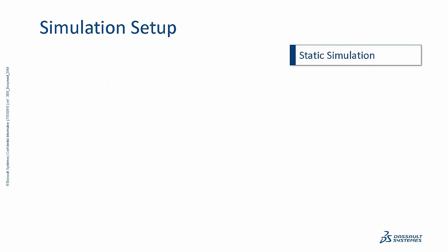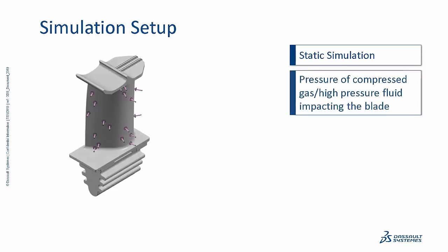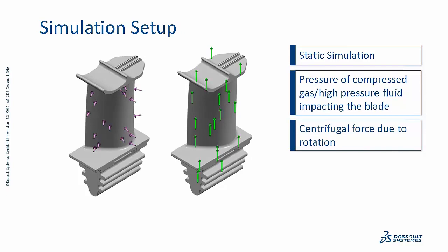So the simulation setup is fairly simple. Again, it was not to an extent where I did multiple load cases, but it was just a couple of load cases. A static simulation was performed. Assuming that we have compressed gas or high pressure fluid impacting the blade from the leading edge to the trailing edge, I applied a uniform pressure from the leading edge to the trailing edge, and I also included a centrifugal